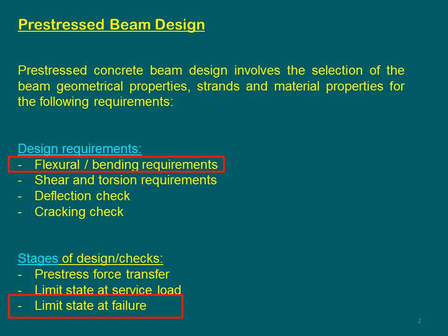When it comes to pre-stressed beams, we have done the stress check, mainly at two cases. The first one was right at the pre-stress force transfer. This is when you apply the pre-stress, it's going to be right at the initial pre-stress force. This is where the stress coming from the strains is going to be high, and most likely you don't have the service load, which means most likely you don't have the additional dead load, and also you don't have the live load.